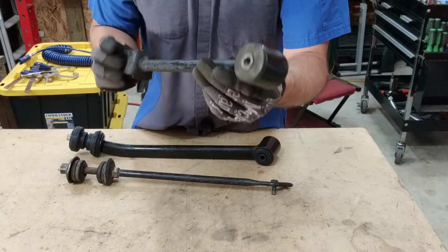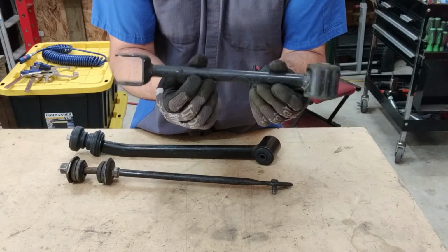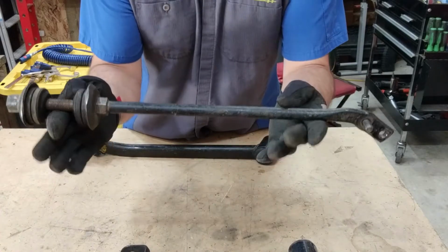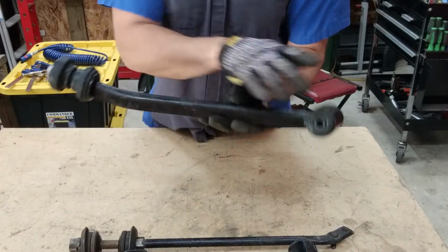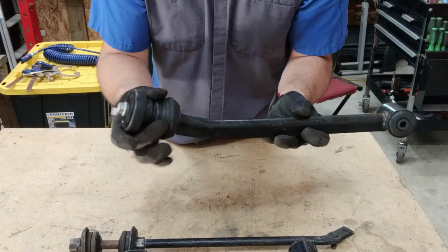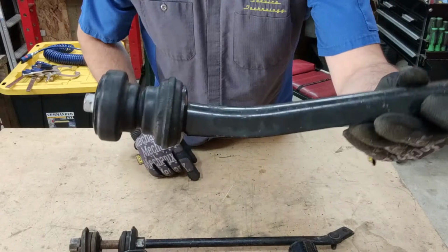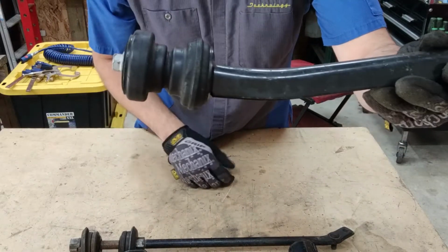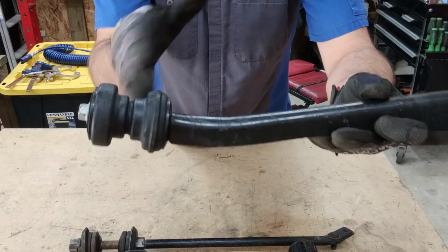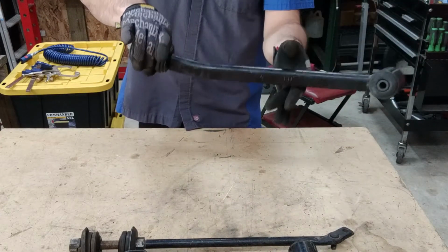This is an example of another tension rod or compression rod, strut rod. And they can be designed slightly different ways. Here's the one from our example. There may be a bushing of this type on one end that connects to the suspension, and it may connect to the chassis in different ways as well. This is a popular way of mounting it to the chassis, where these two bushings would sandwich in between the bracket that mounts it to the chassis of the vehicle and provides that radius function of it.